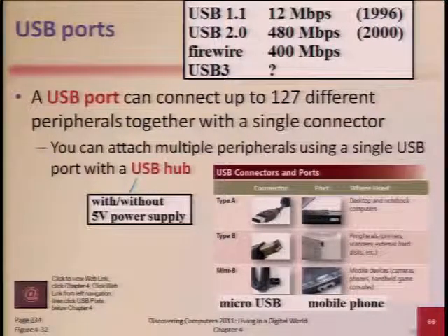You can see how many times, at least 40 times, right? And in fact, because the USB 1.1 was slow, the other standard came into the picture, that is FireWire. Remember the Macintoshes boasted the speed using FireWire. And many a time, because Mac was used for desktop publishing and video editing, they needed a fast connection to connect to video equipment. And FireWire can go up to 400 megabit per second, okay? Compared to the original USB 1.1, FireWire is a lot faster.